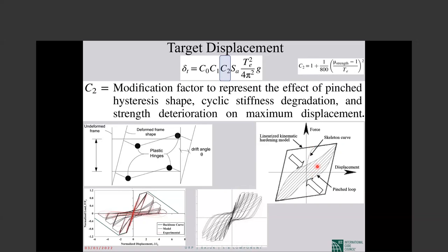And if I assume an earthquake is, for example, 10 seconds, and the period of the building is 1 second, we expect 10 cycles, the length of the earthquake divided by 1. But if the period of the building is 0.5, that is 100 cycles. So buildings with less period will experience more cycles in the same duration.